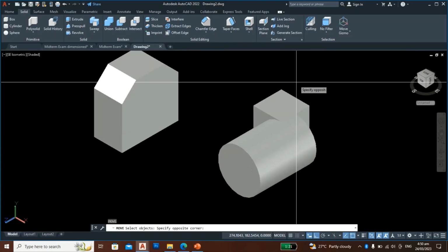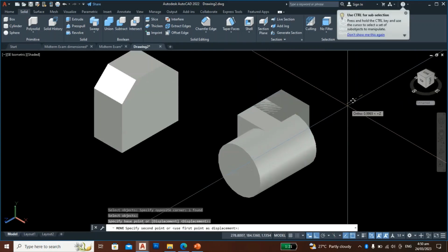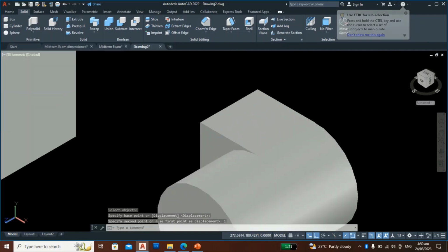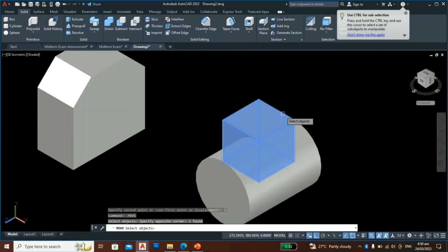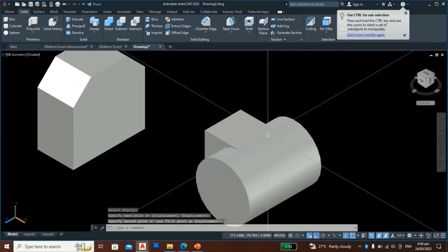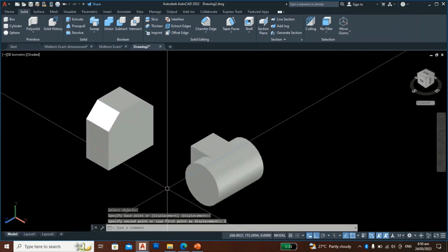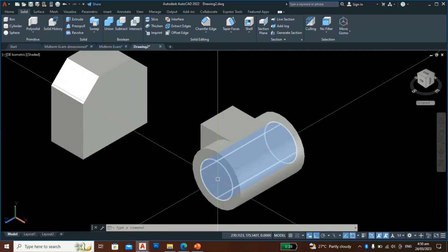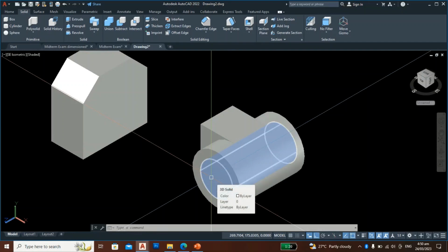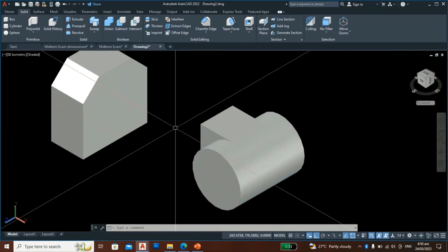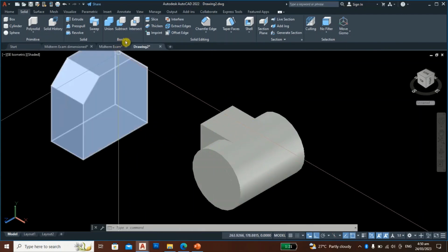Then we have to move again to the center by 1. So move by 1. And another 1. Should be actually 2. Okay. So now it's in the middle. Then we can subtract this to create a hole here. We have to subtract this smaller cylinder from the bigger cylinder. So we will use the command here under the Boolean operations, the subtract.